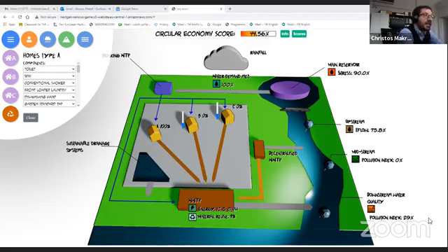But we have to take care of two things. The first is that hydraulic conditions at that specific spot, but also the route between that spot and the wastewater treatment plant, are such that we do not end up with sedimentation, because that would be a problem.